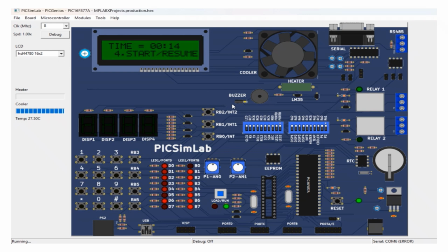During operation, the microwave or grill is turned on through the relay controller. The status LED glows, indicating active operation. The stop or pause function can be selected. The PIC temporarily halts the operation and updates the LCD. The PIC microcontroller continuously monitors the timer internally.